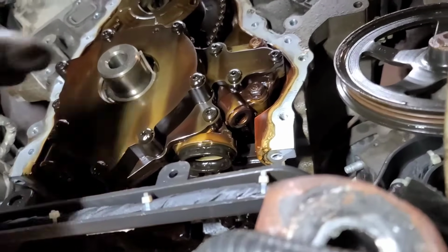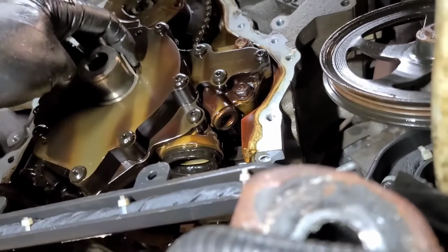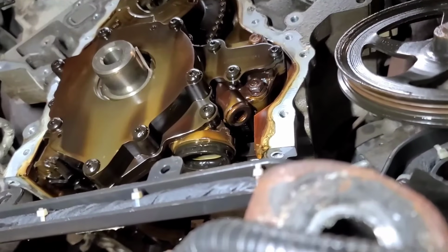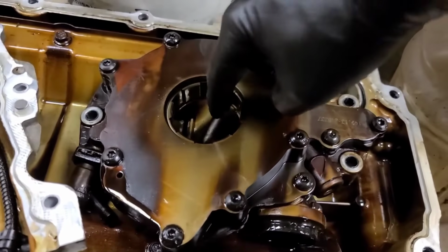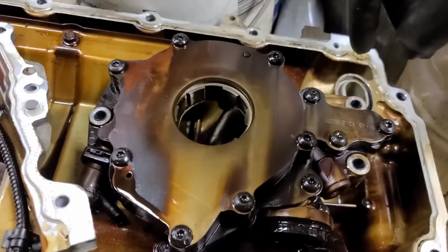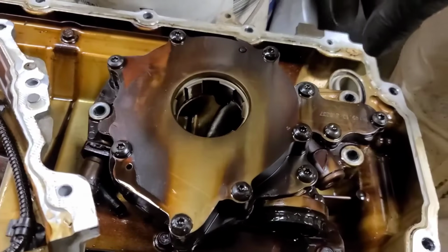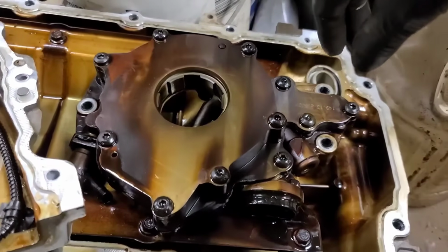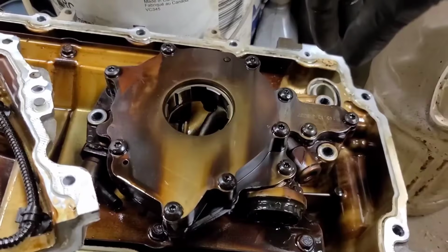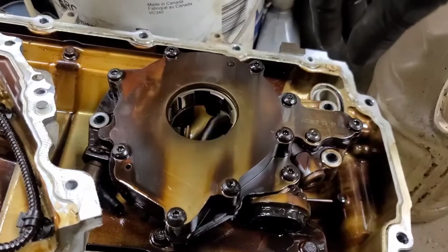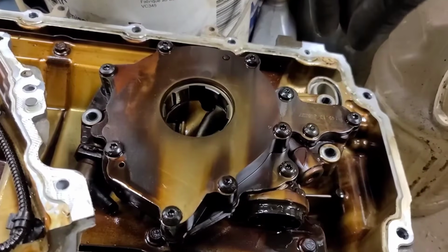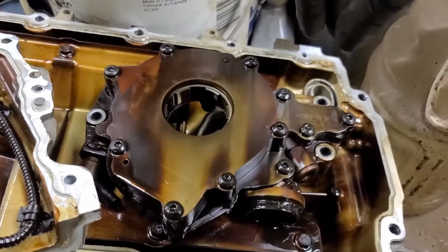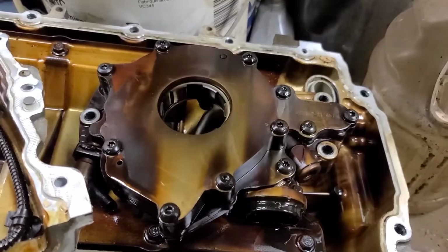I wonder if I have to take this keyway out of the crank. I'll have a look at the new part and I'll see. So no, you don't have to remove that keyway. There's the old pump, 4 bolts hold it on. The new pump comes with 4 new bolts. I'll put a link in the description or a picture of all the parts. That's what I'll do. I'll take a picture of the invoice with all the parts on it that I used for this job. Several gaskets, obviously the oil pump.